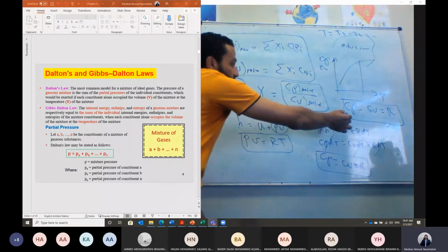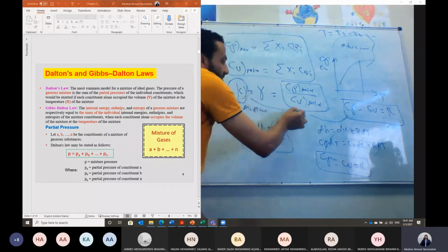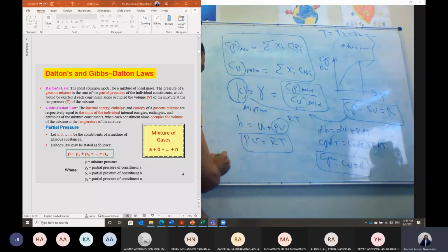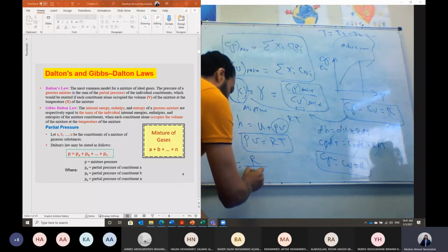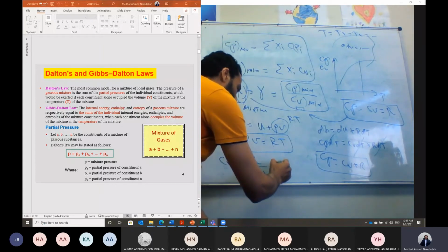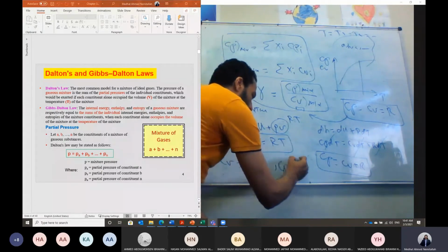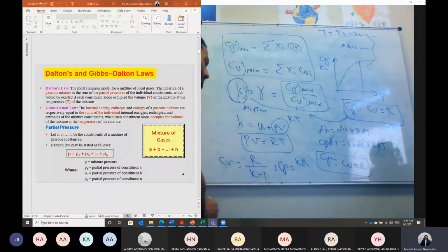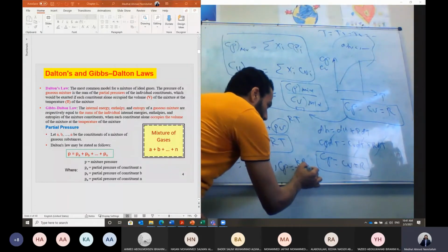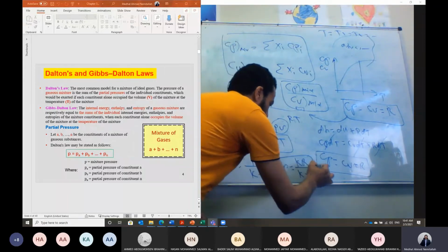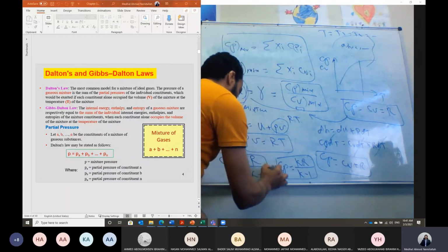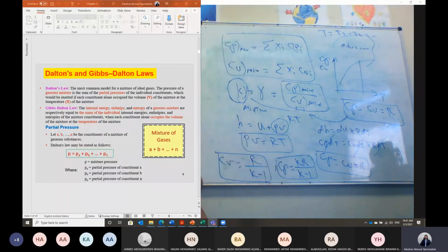If we take this equation and combine it with the specific heat ratio equation, then we can relate Cv will equal R divided by k minus 1, and Cp will equal kR divided by the same, k minus 1. So this is based on the ideal gas relation.